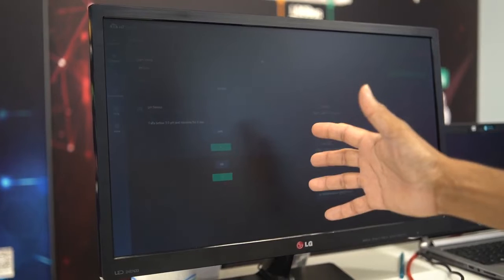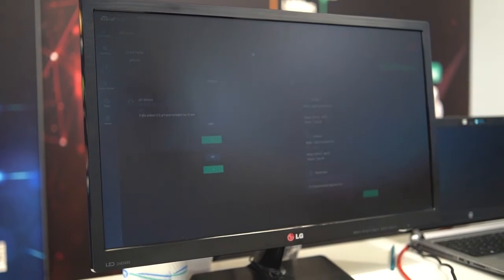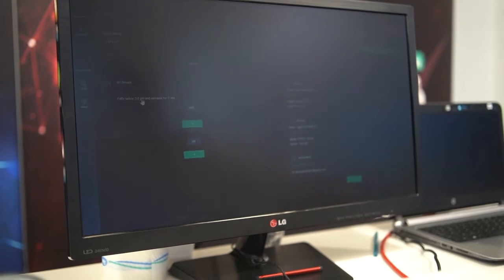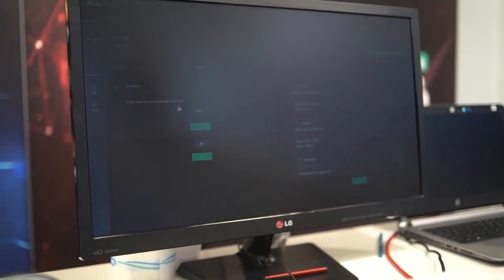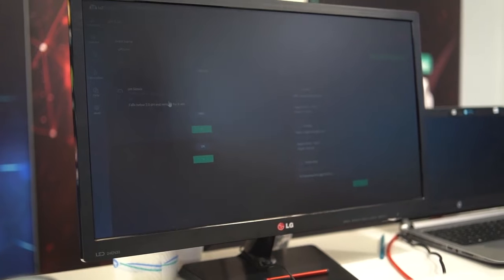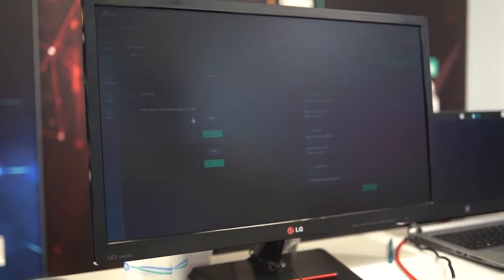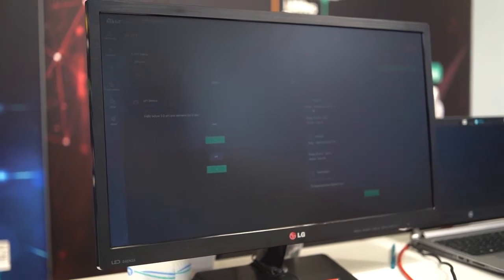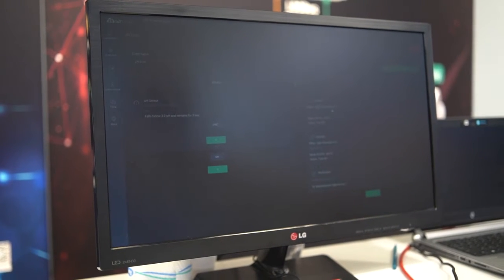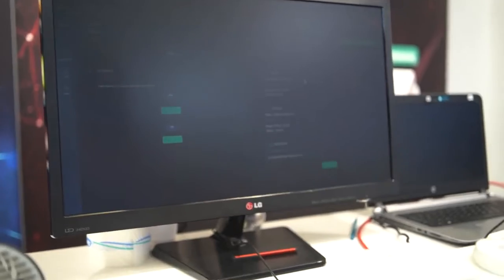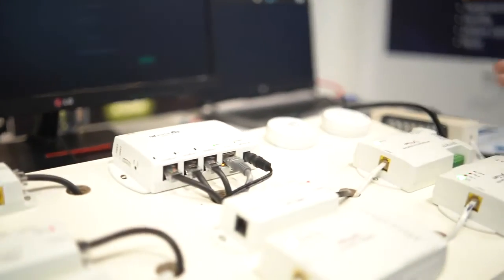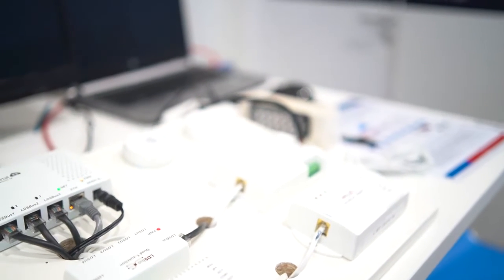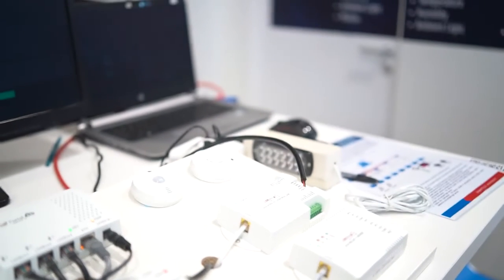So once this condition becomes true, the actions are then carried out by the event manager service that runs in the cloud. So when the pH value drops below 3 and it stays there, in this case I have set it up for 0 seconds, that means act immediately. What will happen is that we have set up actuators here, and 2 relays will be turned on. Both are light controllers. We have relay 1 and relay 2 that control strobe lights here. It could be used as a warning for a process that has gone out of control.